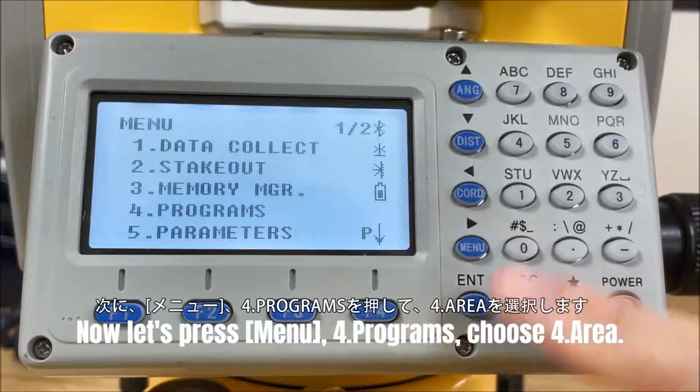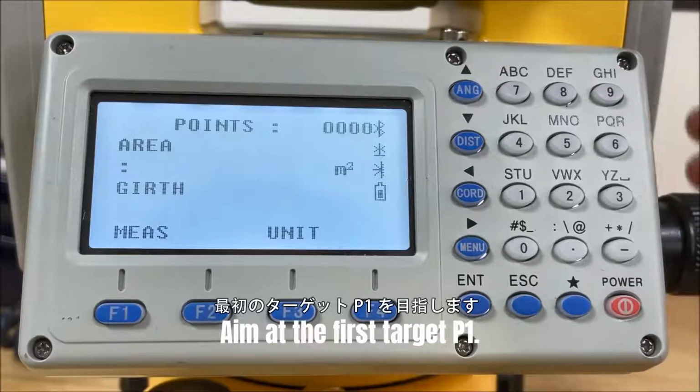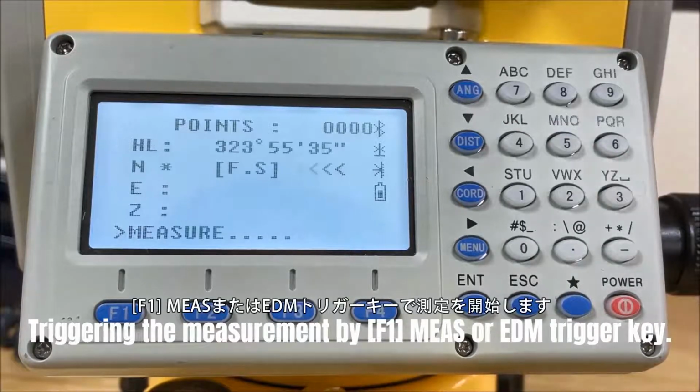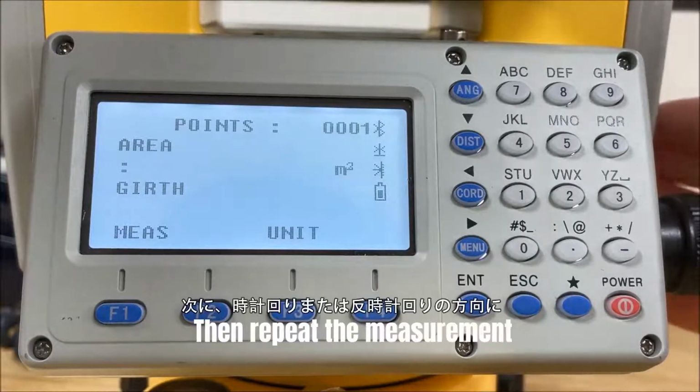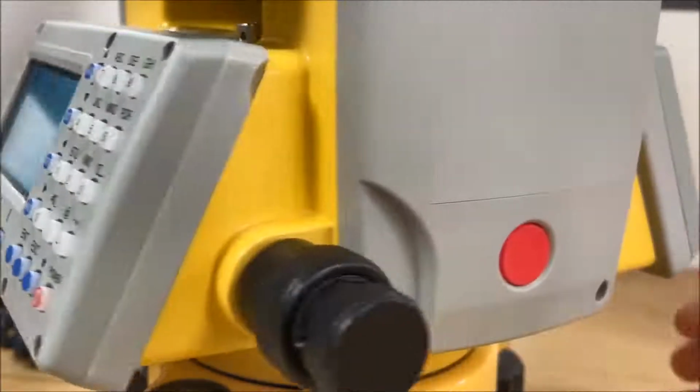Now let's press Menu, Programs, choose Area. Aim at the first target P1. Trigger the measurement by F1 measure or the EDM trigger key. Then repeat the measurement in clockwise or anti-clockwise direction.